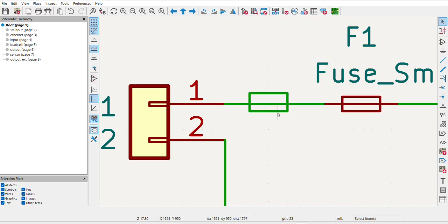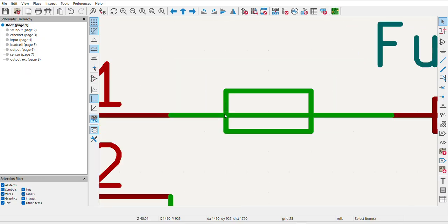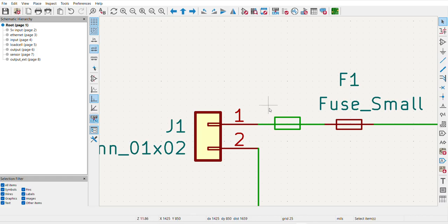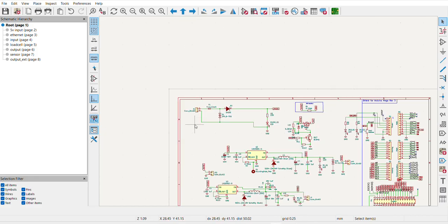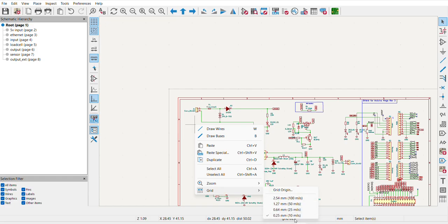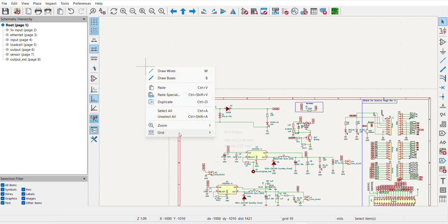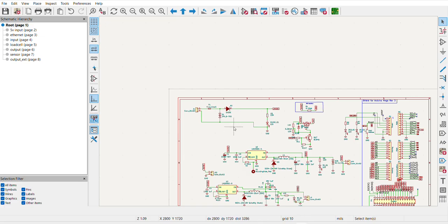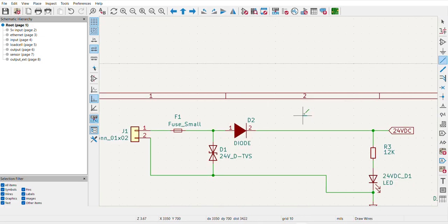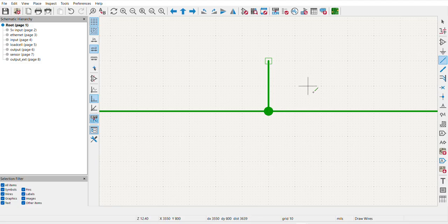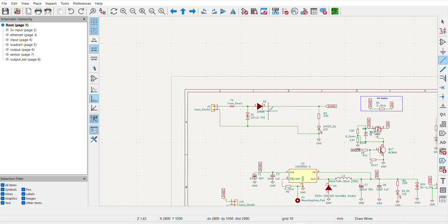So here you can see this is my 2x1 grid box, and it is seated this way. One part needs to be offset; there is around a 10 mils difference that I need to cover with this preference setting. Okay, now you can see I set it to 10 mils. When I need to change mils, I can change it. So now I'm setting 10 mils, and now I am putting in wires. So it is connected. This grid is reorganized this way.